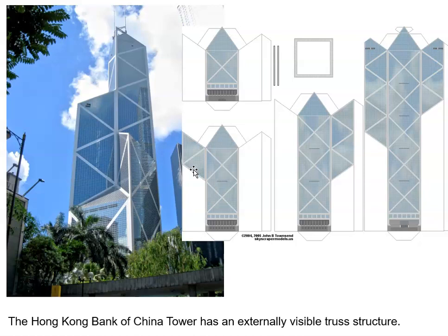So they stopped thinking about it like that, and they started thinking, what if we thought of a high rise as one big structural member itself? They started thinking about it as a truss standing on end. And that allowed for huge developments in high rises. There was no longer that forest of columns that was necessary. So this is essentially a flagpole of a truss just standing on edge.